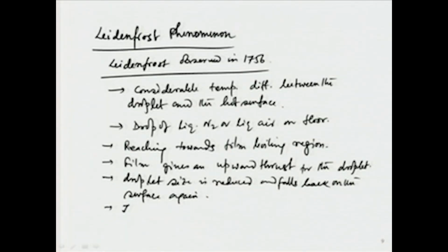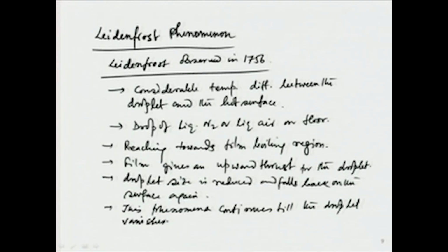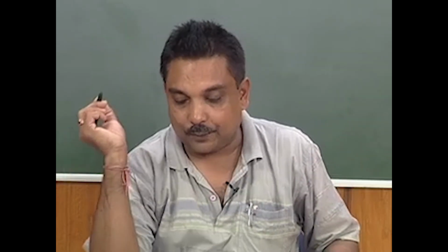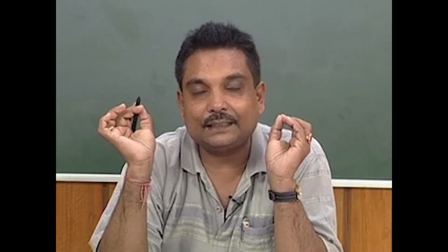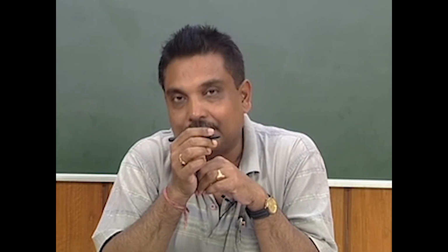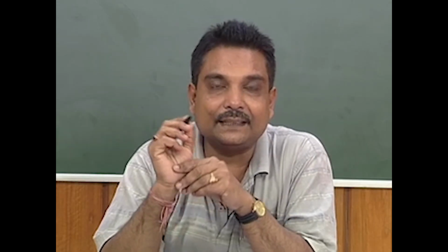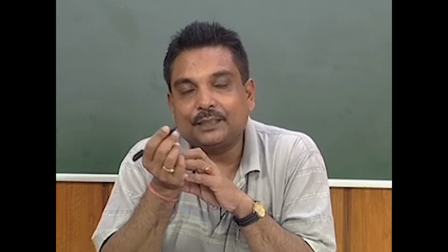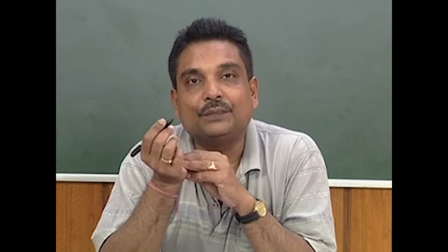So, this phenomenon continues till the droplet vanishes. This is what is called the Leidenfrost phenomenon. This is a very interesting phenomenon observed in the case of droplets falling on a hot surface, and it is linked with the boiling phenomenon and particularly with the film boiling phenomenon.